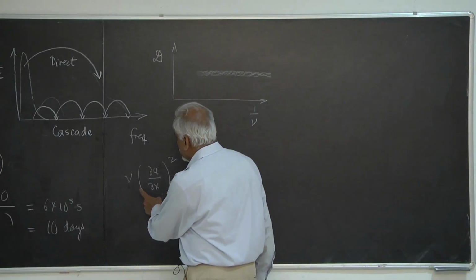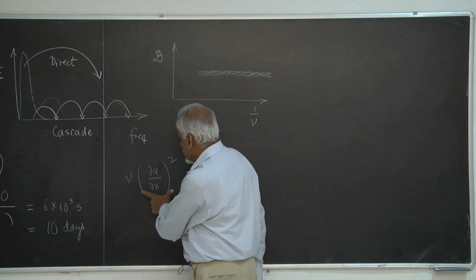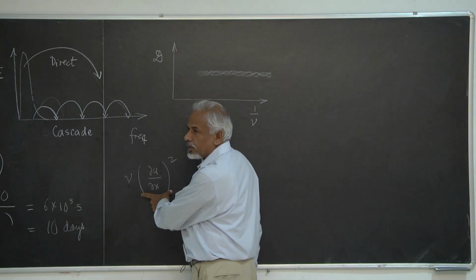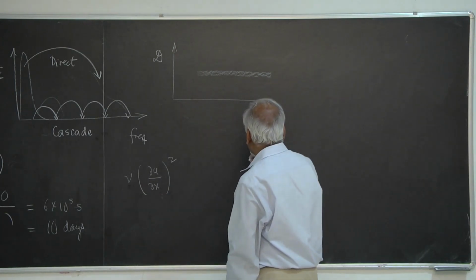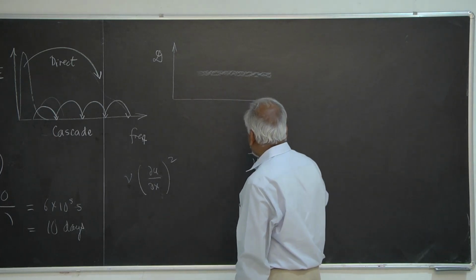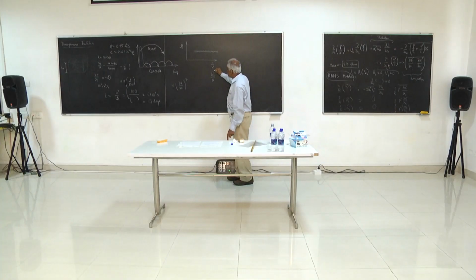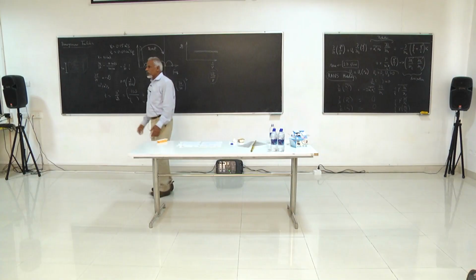So as the viscosity goes down to 0, these gradients become larger and larger. In fact, viscosity is in the Reynolds number sitting in the bottom just as here, so I usually prefer to think of Reynolds number going up rather than viscosity going down.